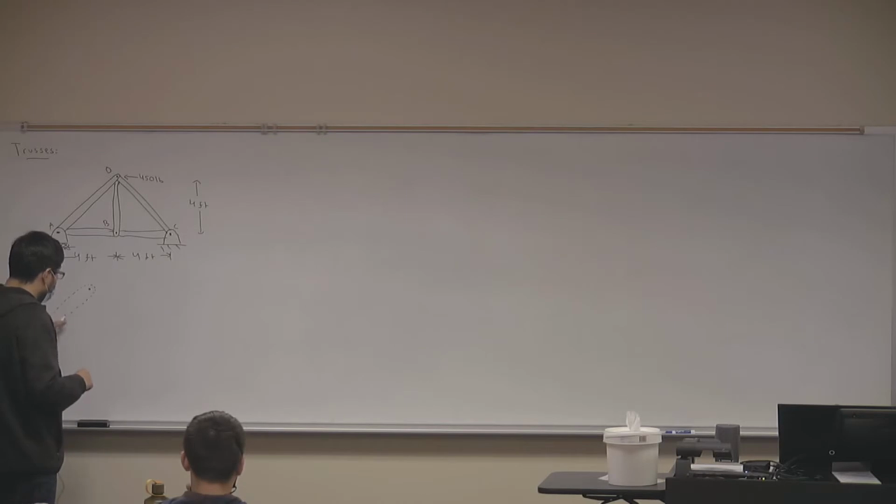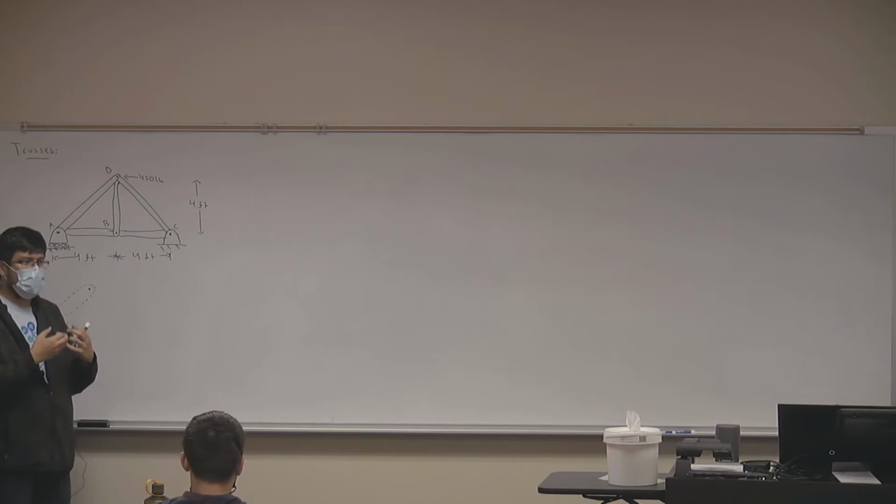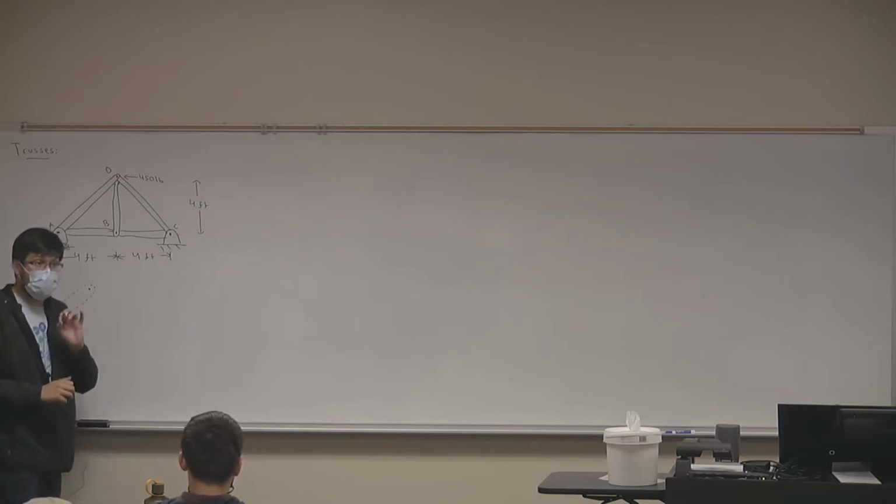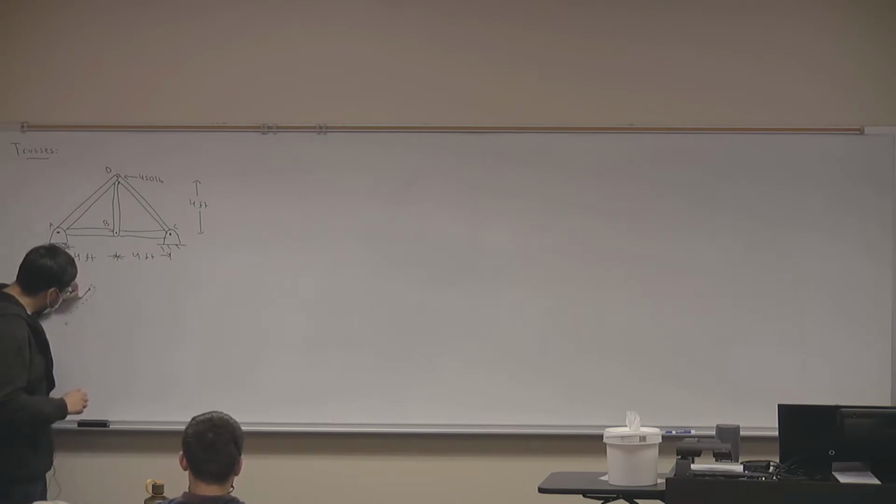So right now, if the truss feels tensile force, you know what tension is, right? Tension? Okay. So the truss feels tension. What is the joint feeling? Is the joint feeling a force into it or out of it? Out of it, right? So when we're studying the joints, our force will be pointing out of the joint.